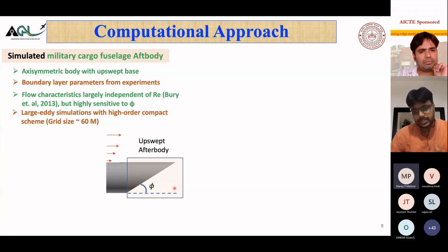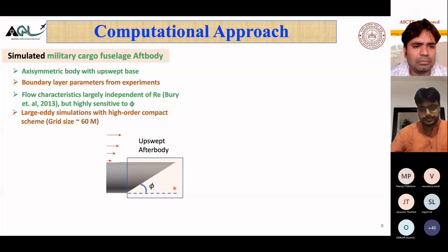Right. So large eddy simulation is something in between, where it will resolve the large eddies, which are of our flow of interest, and the very small eddies can be modeled through different kinds of models. So there is the Smagorinsky model. What we'll be using is called the implicit large eddy simulation, where there is no explicit model, but the filter that we are using basically takes care of the modeling of the very small structures. Okay, and these things I want you to remember, because I'll be coming back to them again and again.